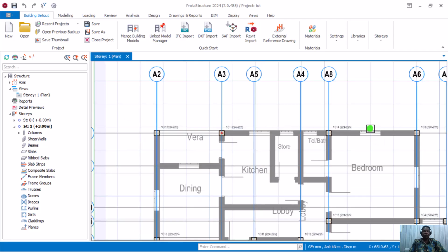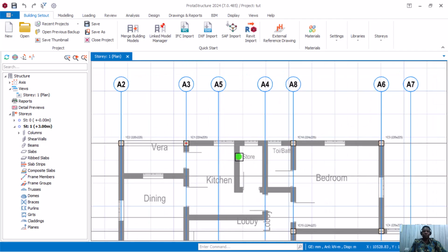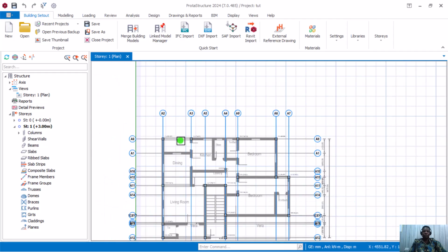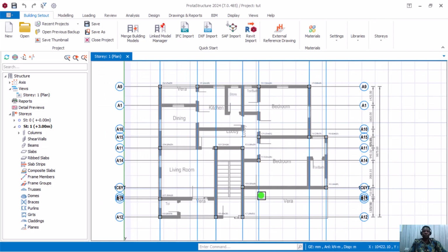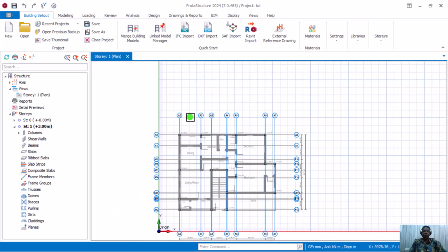These are little adjustments you just need to make on your own, and check the eccentricity. You are still in the same boundary, just about 1 millimeter difference. So you just need to check all the columns which you set, and reconfirm that they are the way you want, before you start your design. And the same thing applies to the grid.